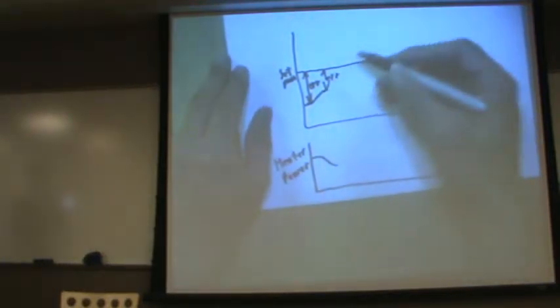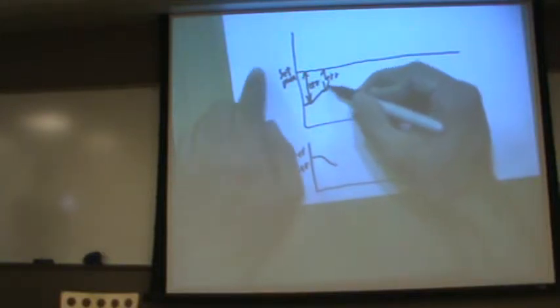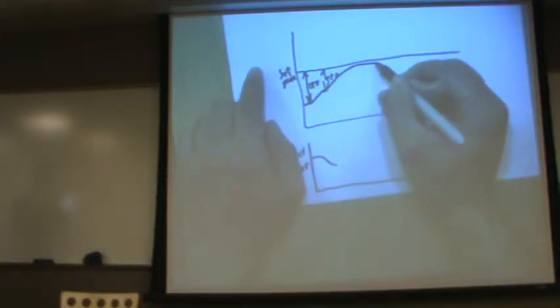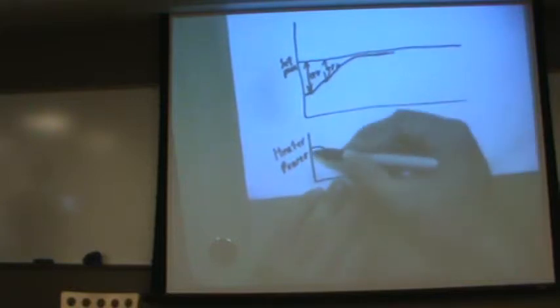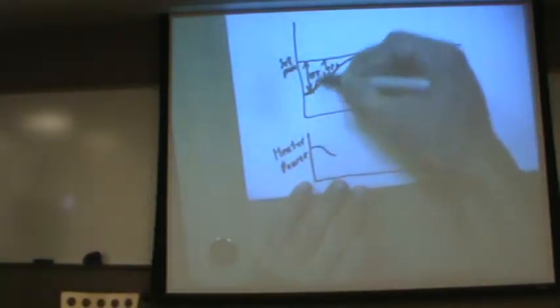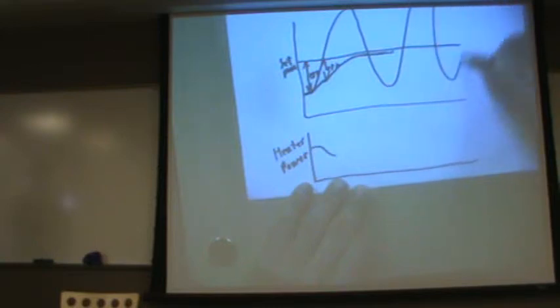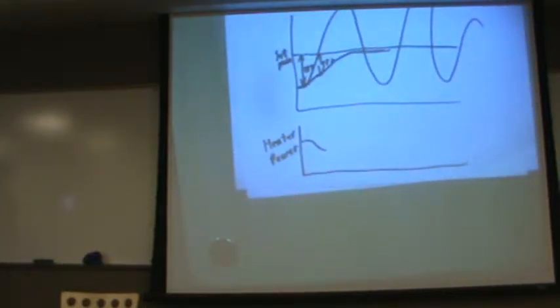And then eventually, if you've got your proportional gain tuned correctly, you will slowly approach your set point. You'll never actually get there because your heater will turn off when you get there, so you'll sort of oscillate below it. This is good. Of course, if your gain is really high, then instead of approaching really slowly, you'll instead overshoot it and just keep doing that, and that's bad. So there's a whole science of tuning controllers that is not the subject of this talk.